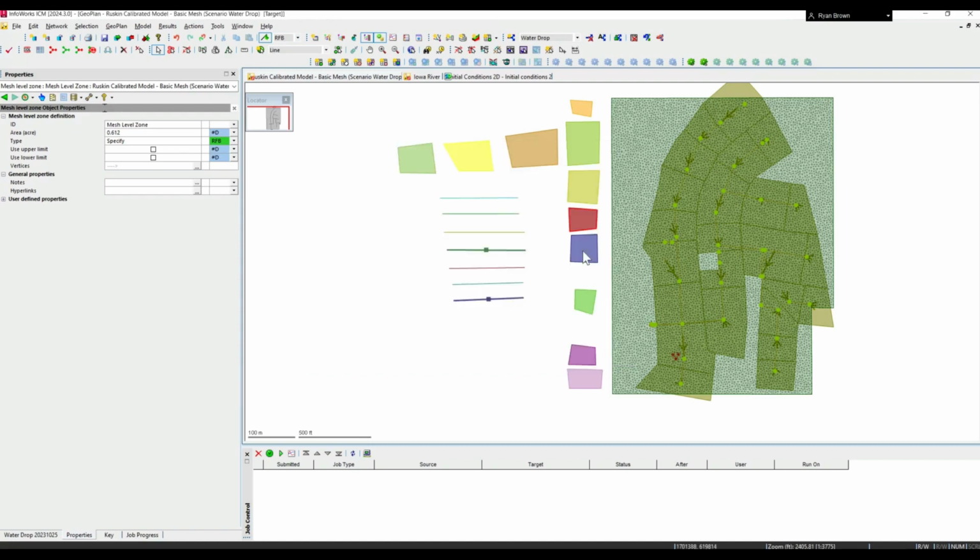So next up, we do have the permeable zone. So with the permeable zone, this is going to be able to limit the amount of transfer infiltrated water to a node. So as you can see here, we have this drains to node, links, subcatchment, multiple links. You will have to use this in conjunction with an infiltration area.